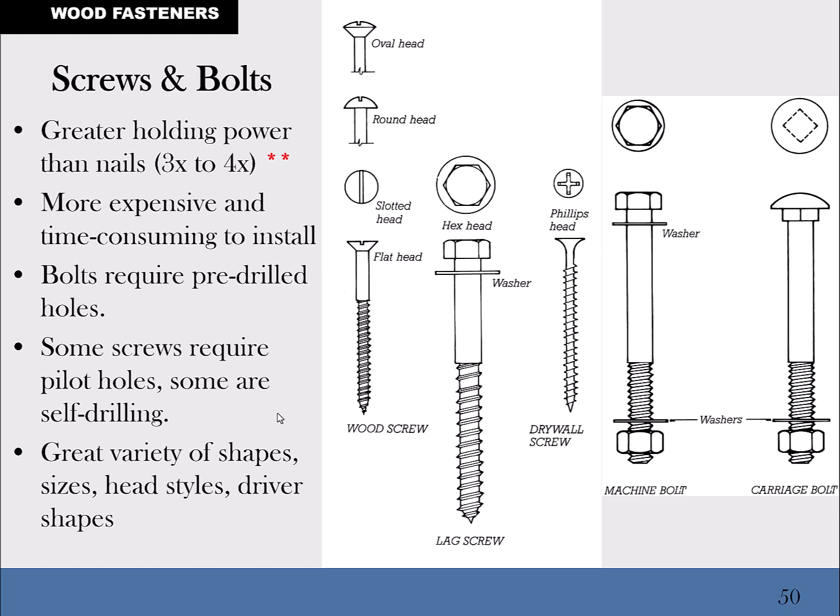So generally, washers help to distribute the load in the wood because you can start tightening if you drill a hole through two pieces of wood and bolt it together, where you could sink the hex head into the lumber where you can't even grab it anymore. And so the washer helps to distribute the load more and allow you to have even more holding power to bolt something together tightly.